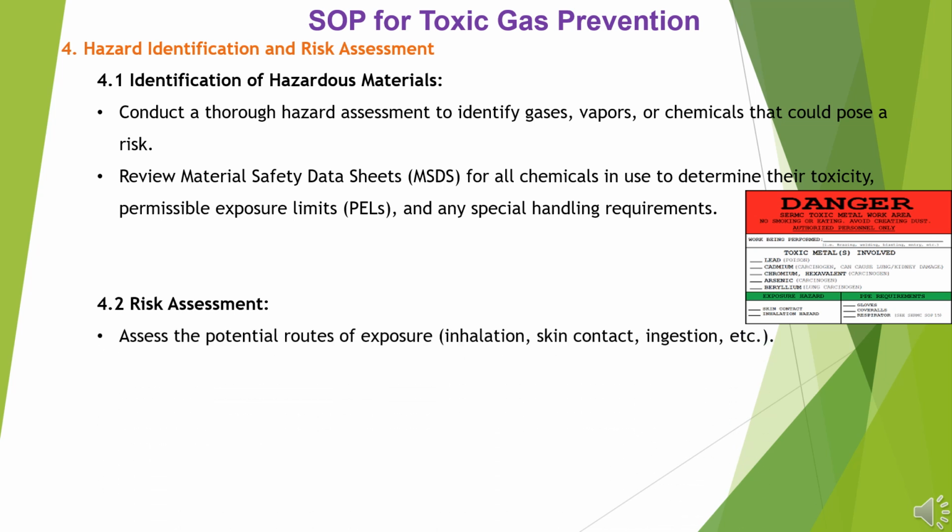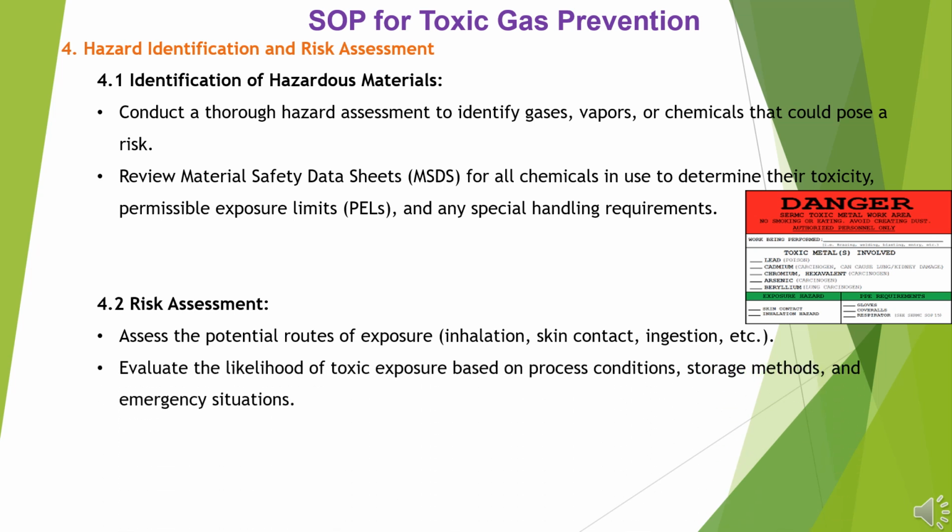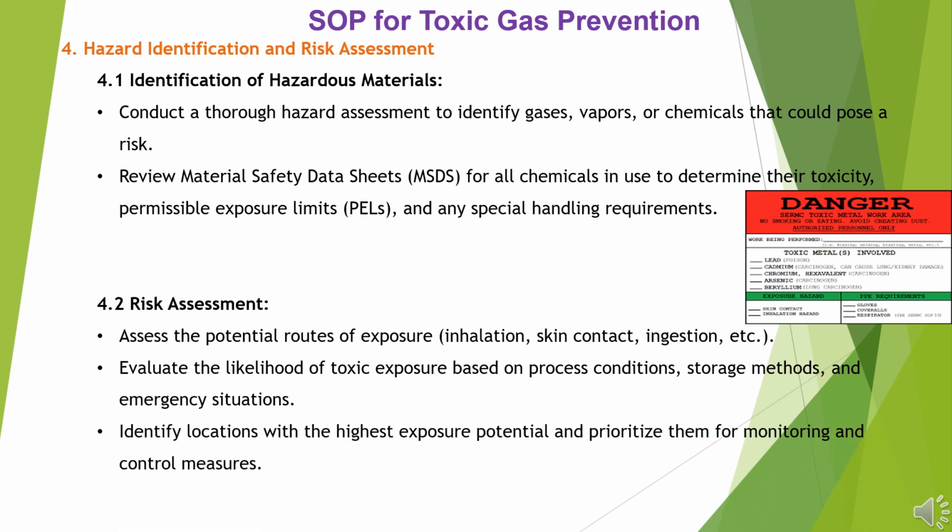Assess the potential routes of exposure, inhalation, skin contact, ingestion, etc. Evaluate the likelihood of toxic exposure based on process conditions, storage methods, and emergency situations. Identify locations with the highest exposure potential and prioritize them for monitoring and control measures.